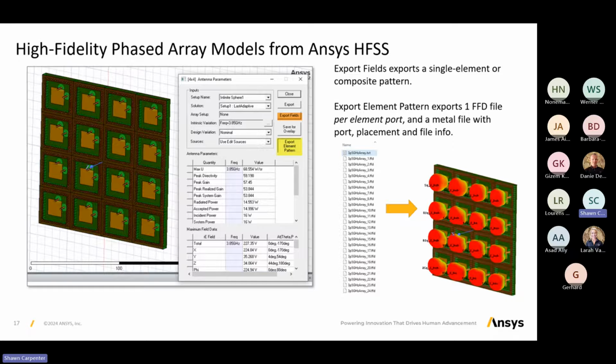So for this 32 port antenna, I'll have 32 individual far field patterns, each of which will be a little bit different because it's unique to the position of the antenna on its array, because you've got mutual coupling effects baked in, as well as proximity and edge effect characteristics baked into those patterns. But these become the basis of a reduced order model to then use in a later downstream shooting and bouncing ray simulation that would use this 32 port antenna as a 32 port source, right? So that I could then start to look at channel characteristics appropriate for MIMO systems and MIMO signal processing.